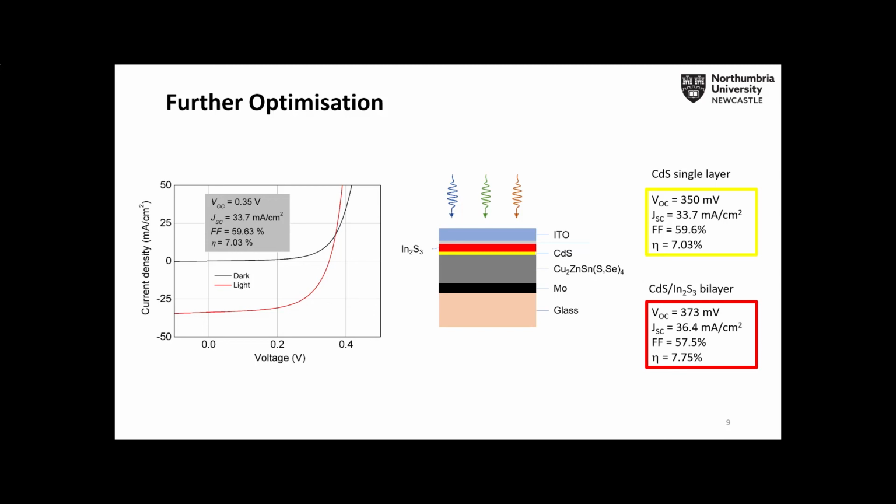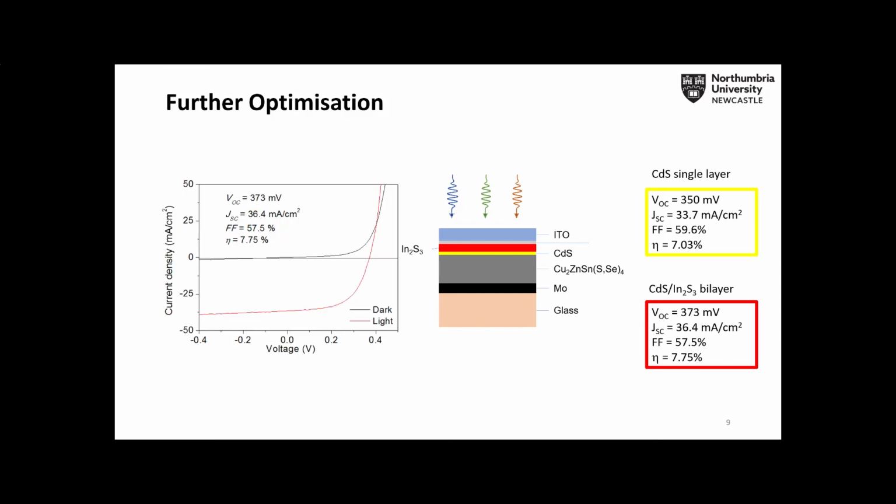There's still some cadmium sulfide, and that allows us to increase the efficiency, notably both the voltage and the short circuit current, so that now we reach around 7.8%. Accounting for grid area, I think this is going just over 8%. So this is an intermediate step, but a step in the right direction in terms of reducing cadmium.